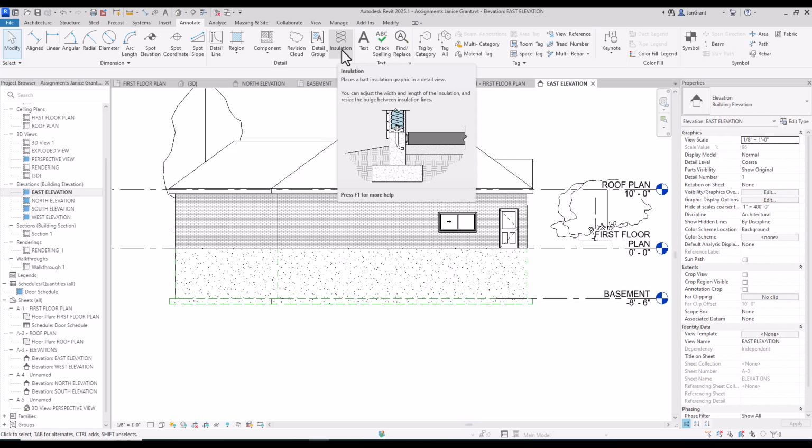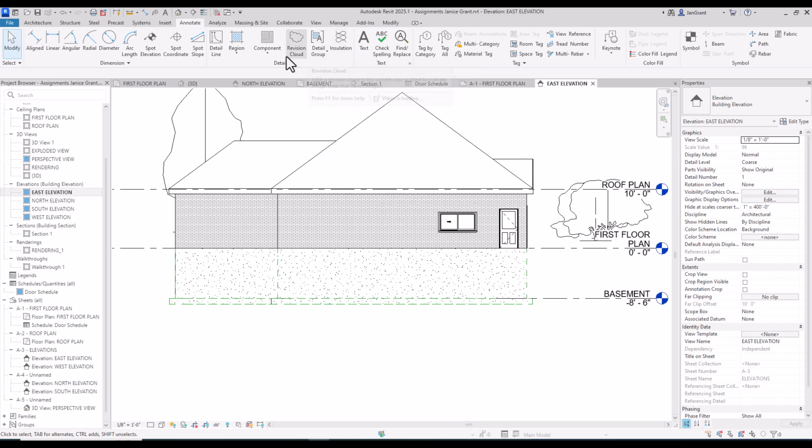So you cut a wall section and then enlarge the scale of it, and draw the insulation and use properties to change the width of that insulation. We also have components that we can draw, and those components would be loaded, like the wood for the top plates and the bottom plates. I'll post a video for that you can look at if you're interested in that. But what I want to really show you is, well, one more thing is detail line.